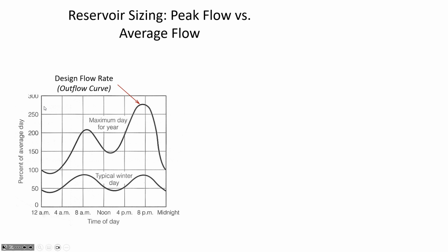And so if you have the water coming into the reservoir at a constant rate, then you're able to draw from the reservoir at a variable rate. And then it all works out if the reservoir is big enough. So you want to make the reservoir big enough so that there's always enough water in the reservoir to meet the demand, but you don't want to have the reservoir too big, because then that's a waste of money and you've oversized something that is very costly to construct.